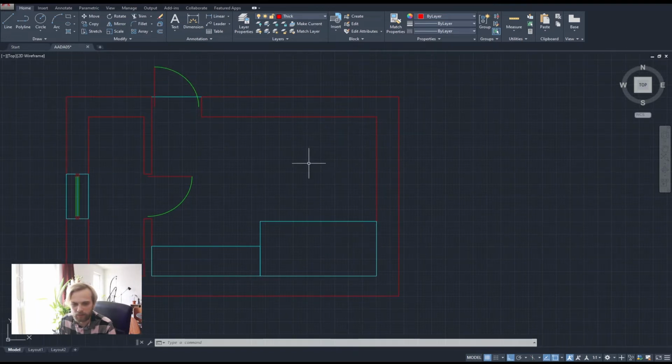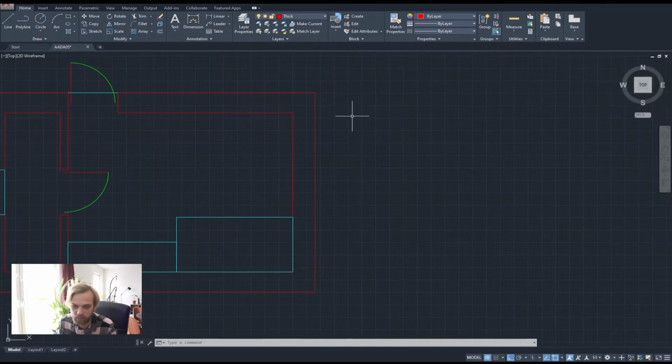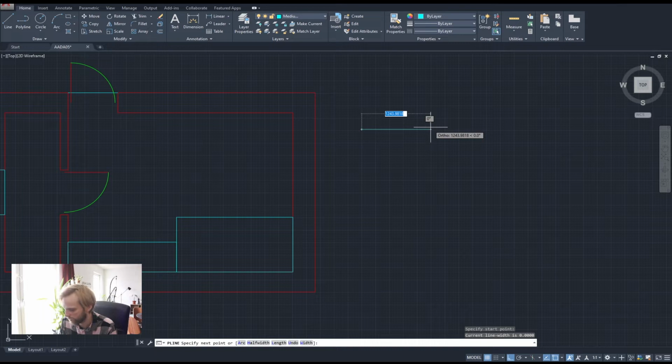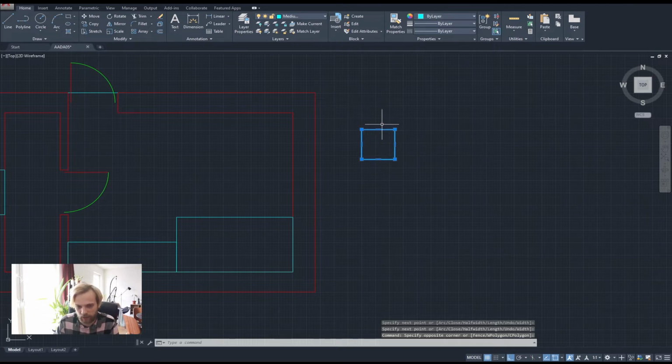So now I need a kitchenette, right? Kitchen cabinets always have the same module size, and it's always 60 by 60 centimeters. The refrigerator, the stove, the sink cabinet, all of them have 60 by 60 centimeters. That's not regulation, but the default value, let's say. So I'll switch to medium, and I'll just create that single rectangle of 600 mil by 600 mil, like that. That's our single segment for the kitchen.